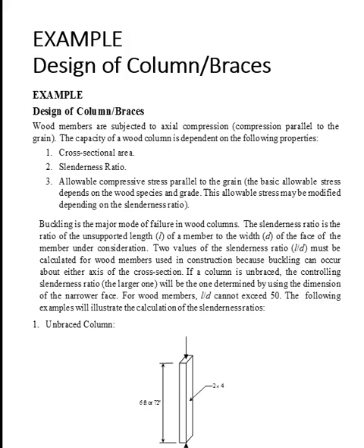So again, we go back to the tables we looked at earlier for different types of wood, and that's where the optimal type of wood or species comes from. And you can change the stress based upon the slenderness ratio, obviously. If you've got a thicker piece of wood, which changes the slenderness ratio, there's a balance between the two.